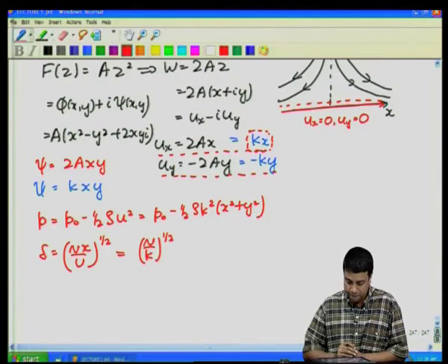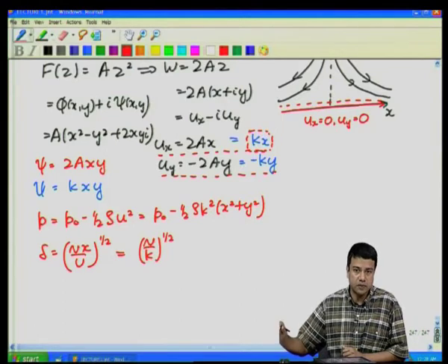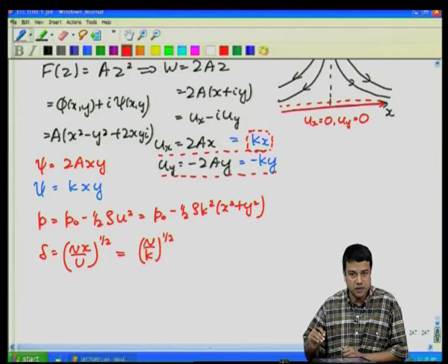The reason is because the mean flow velocity itself is increasing as a function of x. The boundary layer thickness will be determined by a balance between convection, that is sweeping momentum downstream, and diffusion, which is transporting momentum from the surface into the flow. For the Blasius boundary layer past a flat plate, the convective velocity, the mean flow velocity, was a constant.